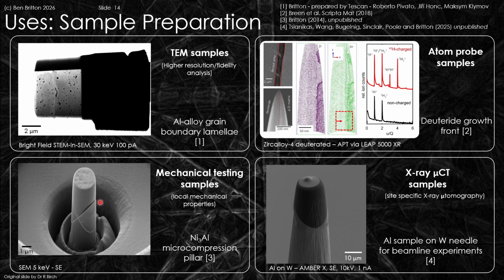And here we've deformed the object with a controlled deformation, and we actually get 3 slip systems operating in this example. We can do site-specific lift-outs to enable us to do atom probe tomography. This example is shown in a lot more detail later, but this is really nice to do atom probe tomography to look at particular interfaces.